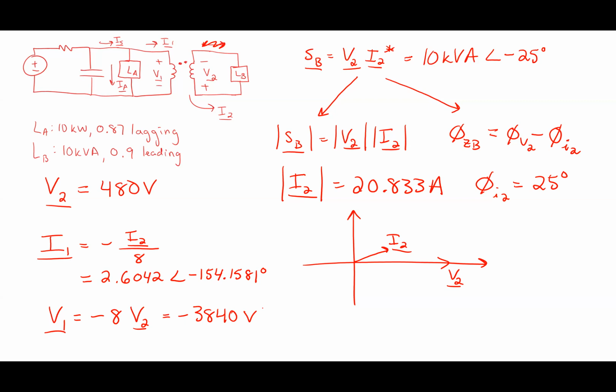All right. So you would never define this this way. But what this actually tells me is that the voltage should have been written with the opposite polarity and the current should have been written with the opposite polarity, so that in my mind, I know the power is going from that source to that load. All right, don't worry yourself with that too much. This is a weird definition that I gave on that transformer. It's just to really practice you for something that you could see. You'd never see somebody at Duke defining transformer polarities like that.